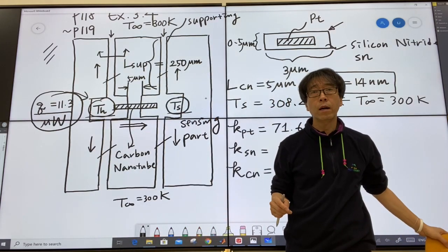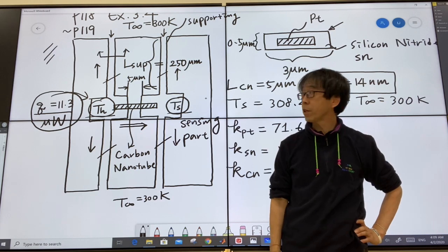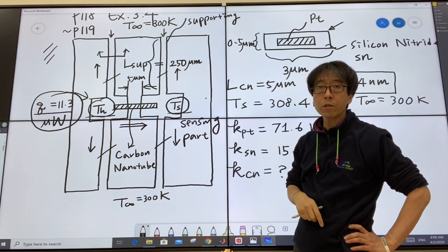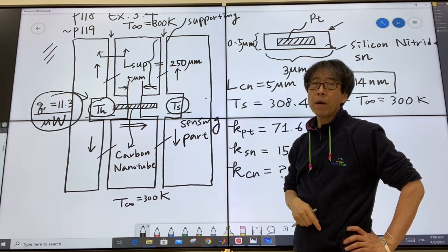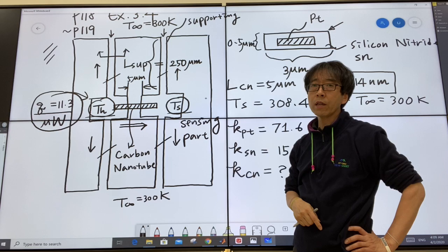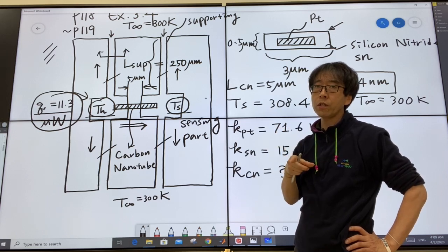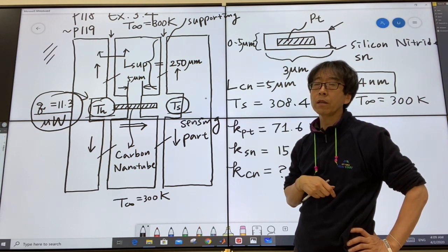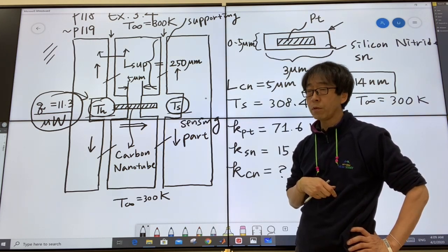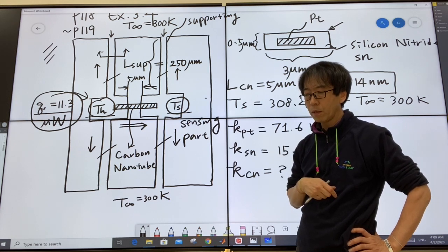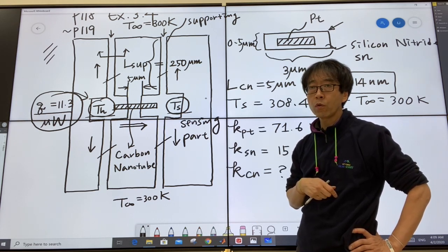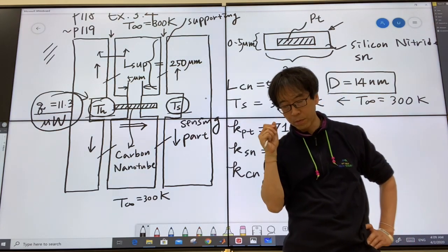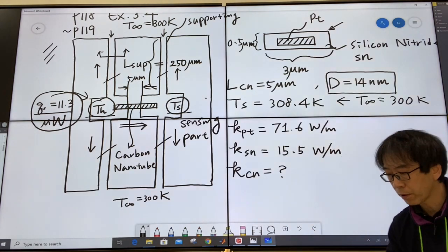represent the temperature change, because platinum resistance will actually increase as temperature increases. How much is it? It's about 4 ohms increase per 1 kilo ohm of resistance per 1 degree Kelvin. It doesn't look like too much, but it's a pretty reasonable value which we can measure with precision electronics. I'll talk about such electronics later on, but today, let's assume that we can measure it.